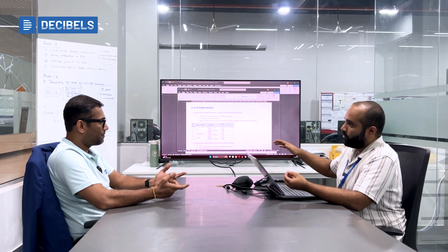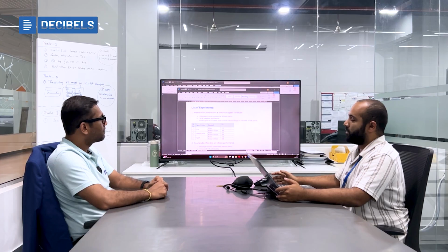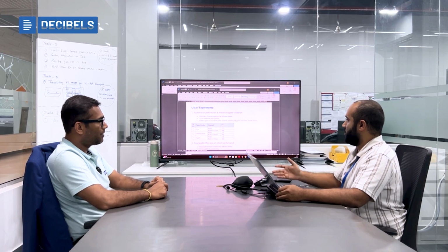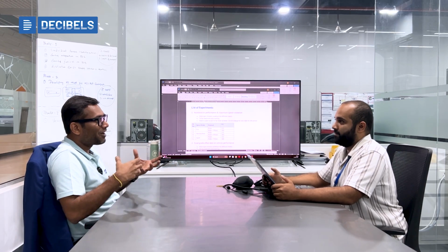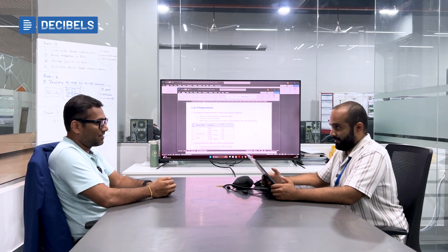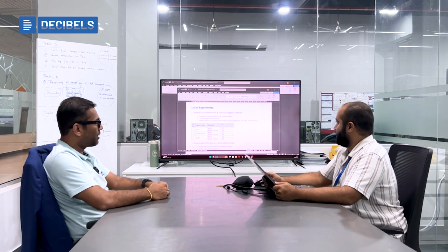Having that covered, slowly we will move on to the experiments, where we'll go much more in depth on the tests and experiments that will be run on the Dyno. Just to add one more point on prototyping: when you do it on the road, it is not possible to repeat the same test cases in the same manner. Exactly. If you tune something, you want to see a change, and if you take it on the road, you will not know the impact of that change on the vehicle. Interesting. Go ahead, I would like to hear more about it.